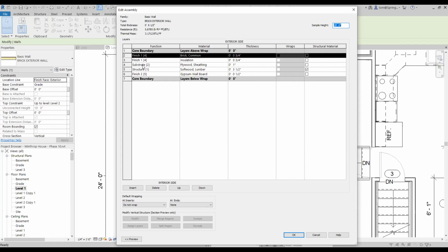So why is it 3/4? Well, for this particular one, I was going to build a vinyl sided house, but the actual code for that neighborhood was that you had to use brick. Instead of changing it, it would have been a whole lot more expensive to go with full brick. We use this 3/4 inch brick stuff. It was actually a brick veneer. So we used that. It was real brick.